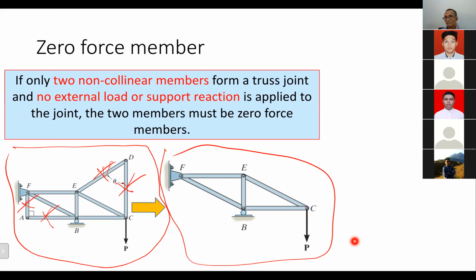Sir, I have a question. Does zero force member actually mean that they don't have any load, or they're just in equilibrium? In that particular condition, like this one, the load there is zero, no load actually. So it's unnecessary. Oh no, you cannot say it that way. Only in this particular condition, Azhar, yes, it's unnecessary.